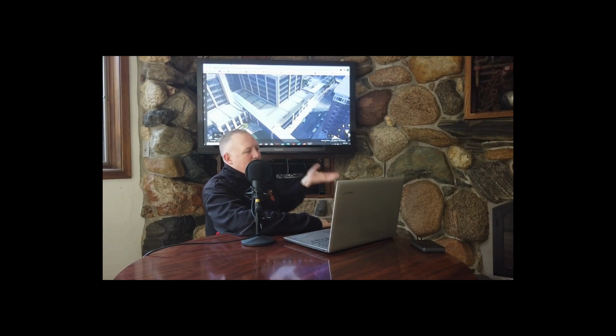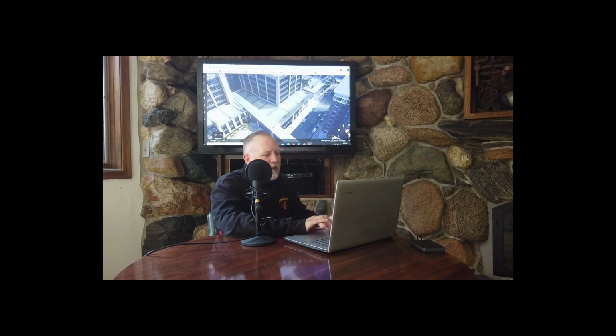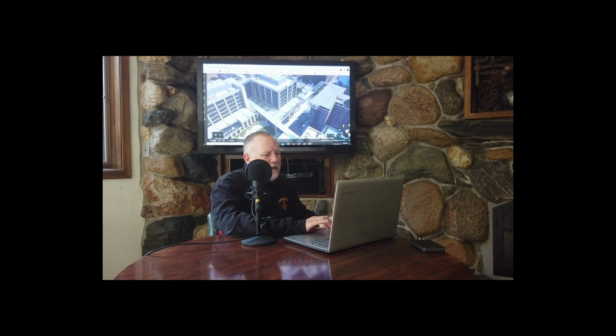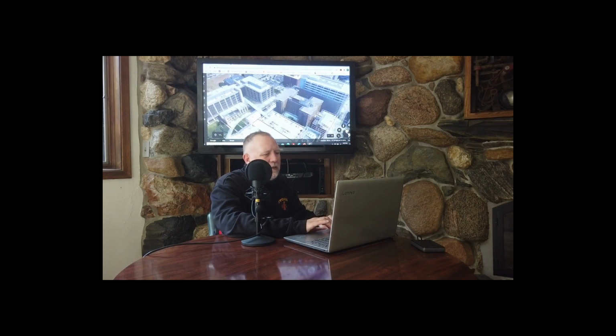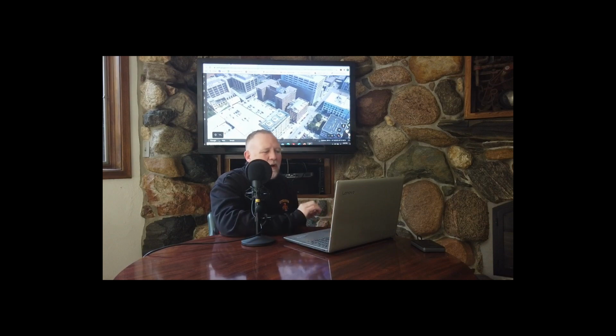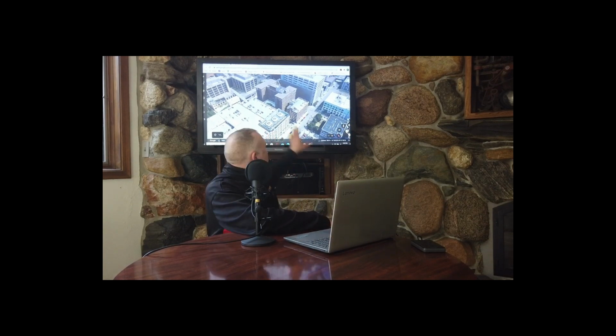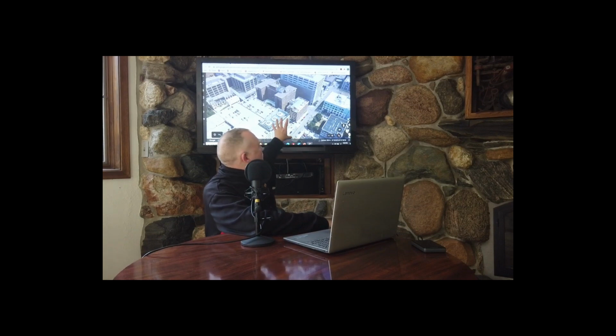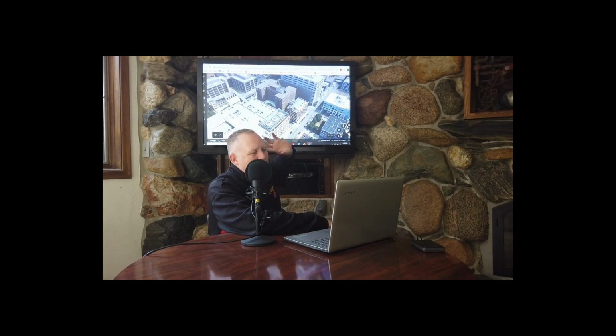It's in the skywalk, but it's below where people walk. So this makes just an ideal place for a cooling tower. Now, they have a chiller because it allows them to put it all the way over here. They went with an air-cooled chiller because of the massive capacity of this particular plant.